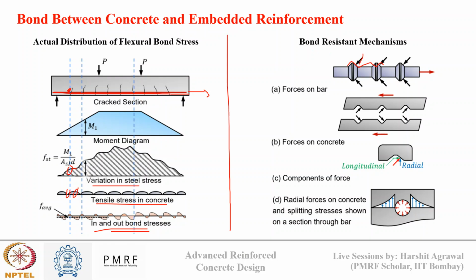the pull force that is acting on the rebar is generating some downward effect on the ribs, and this will generate some outward effect on the concrete. Okay, so that's why just near the ribs there is maximum bonding, and as we move away from the rebar, the bond strength decreases continuously because of this force element which is resisting the pull.